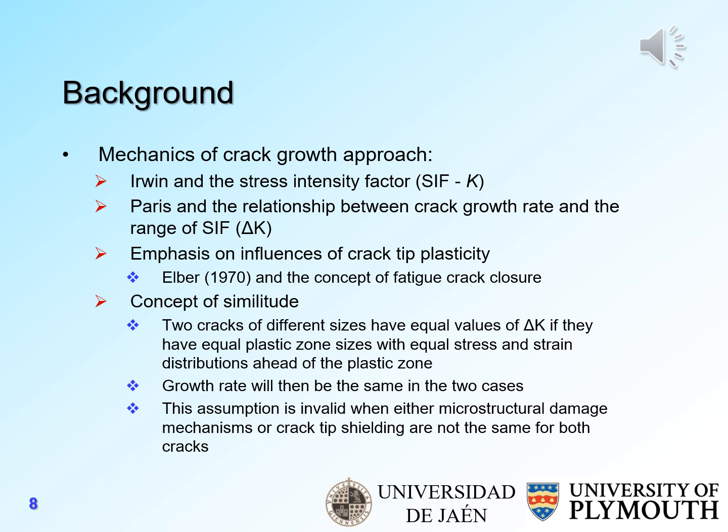Perhaps in contrast, in the mechanical engineering community, there was more of a mechanics of crack growth approach. So you get Irwin and the stress intensity factor, which is an elastic parameter that characterizes a plasticity-induced phenomenon, or a certainly nonlinear constitutive phenomenon. Paul Paris and the relationship between crack growth rate and the range of stress intensity factor, and influences of the crack tip plasticity, for example, Wolff-Elber, and the concept of fatigue crack closure. You also got the concept of similitude.